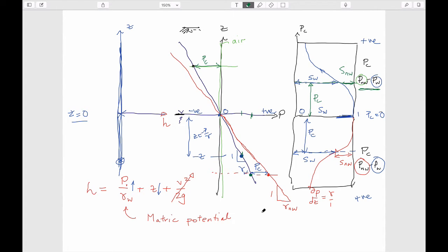You can, because you could use Darcy's law, of course. But we know that, for instance, Darcy's law is equal to hydraulic conductivity times the gradient of head, right? It has these other elevation terms if you do it in terms of pressure, right? So if you did it in terms of pressure, there'd be some other terms. But this is the easiest way to do it. Let's do it this way. This is for flow in the vertical direction. What's the head gradient? dH/dz.